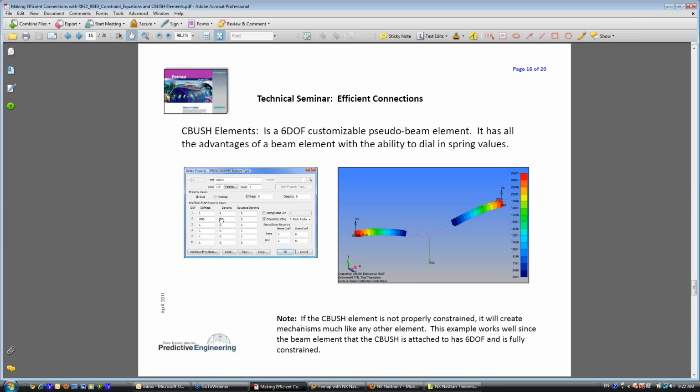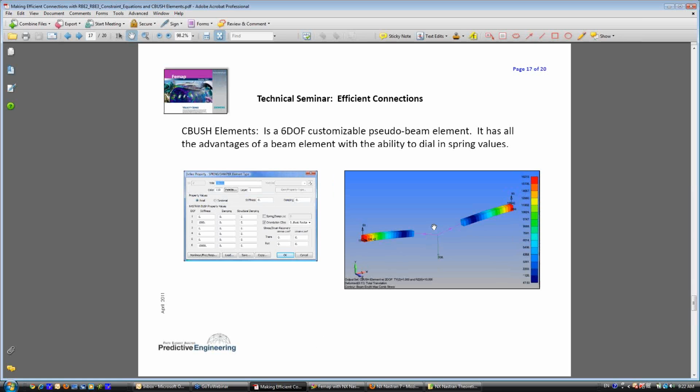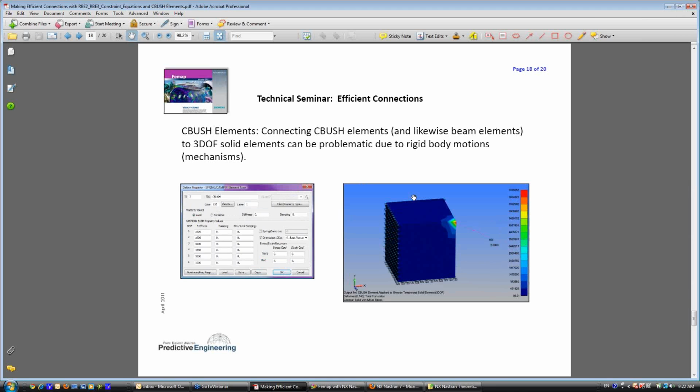So setting it up, you have to cover 6 degrees of freedom. If you're using it on our simple beam model, it works perfectly because 6 degrees of freedom are covered here on the beam. Here is my setup. I just want Y. I have it set to the orientation system Global, Y is vertical. Simple, clean, done. You can also have it transfer rotation. Just put a rotation coefficient down. Very direct.